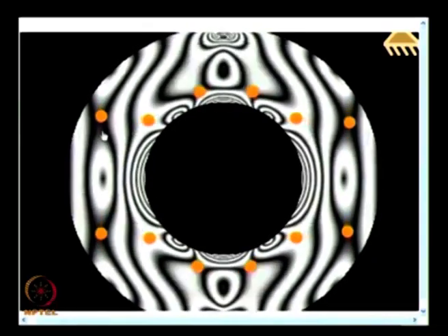And this is more like verifying how to check the ordering of fringes, because for a saddle point we know in one direction the fringe should increase, in another direction the fringe should decrease. So, whether this feature is captured is what you will have to look at.